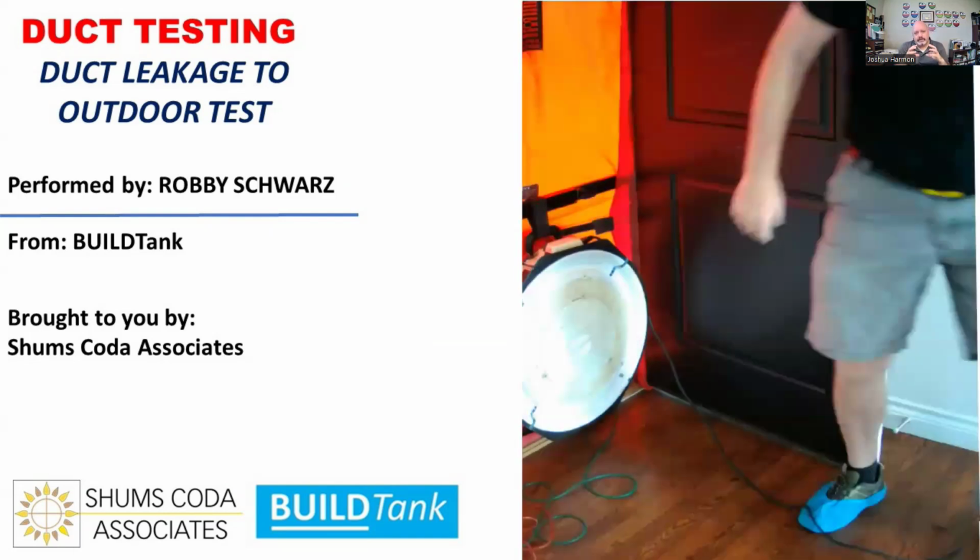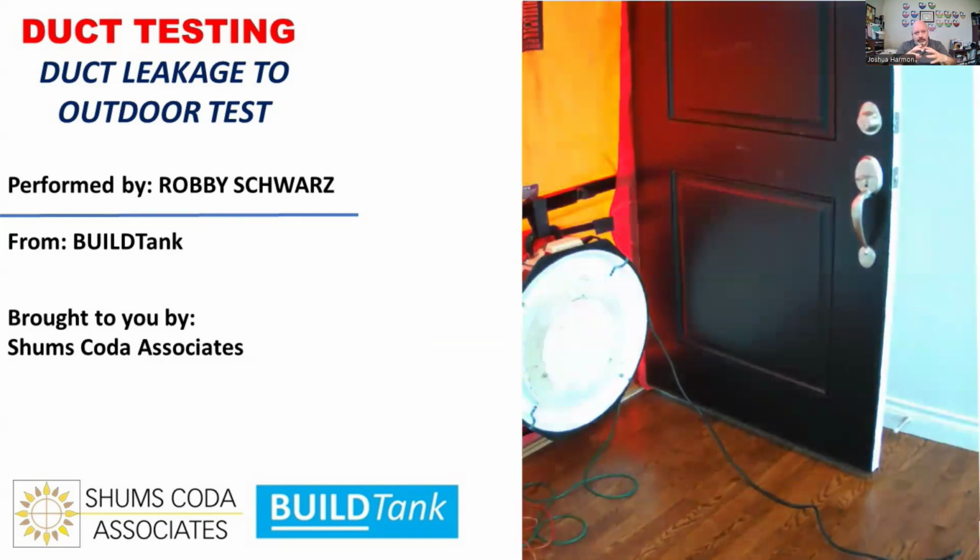And like you said, what we're doing is very similar to a blower door. A blower door test would be the entire structure being pressurized and identifying leakage over time. And what we're doing here is he's pressurizing the home, and then the duct itself will be following that same pressure. With the blower door, we're just testing the building, and you isolate out all of the duct. Now he's including both. I need to cover this inlet to separate it from the outside. And then we'll do our baseline pressure here.